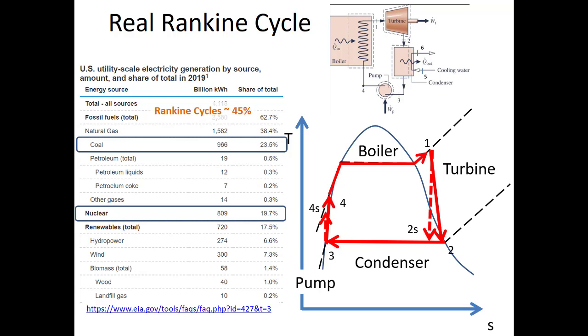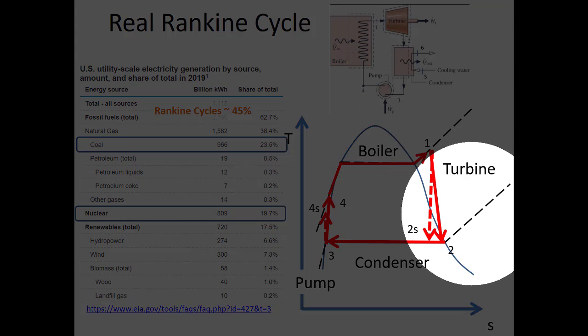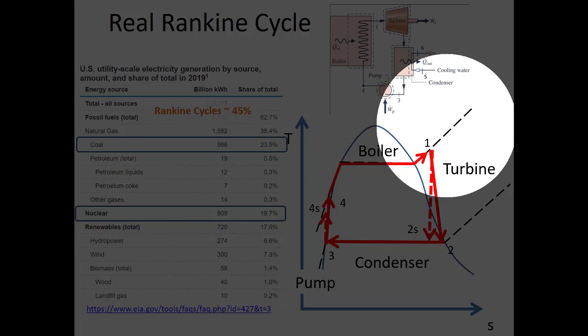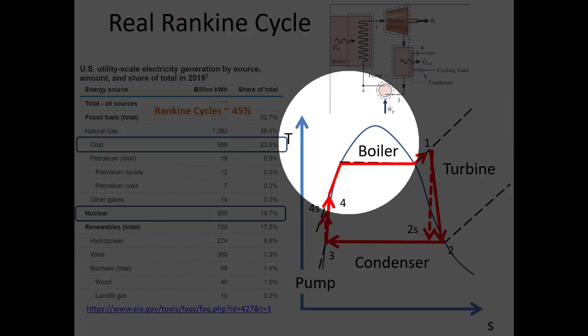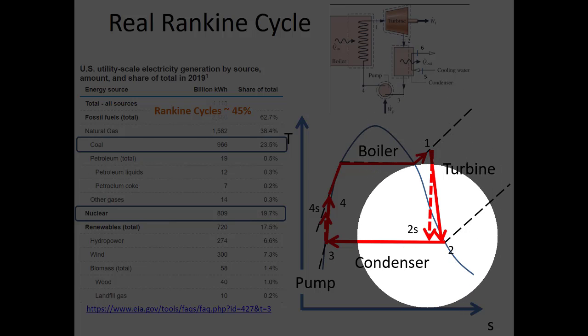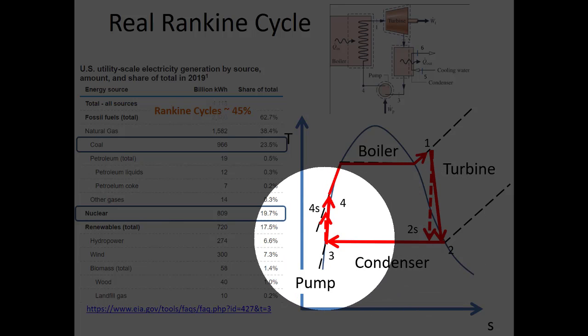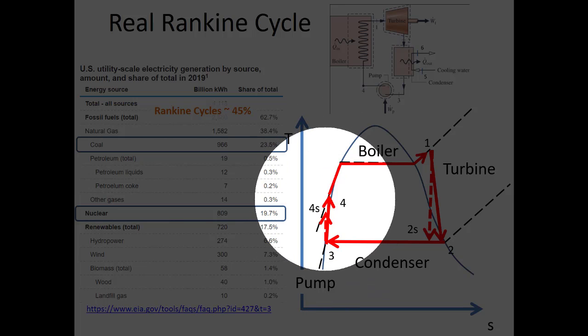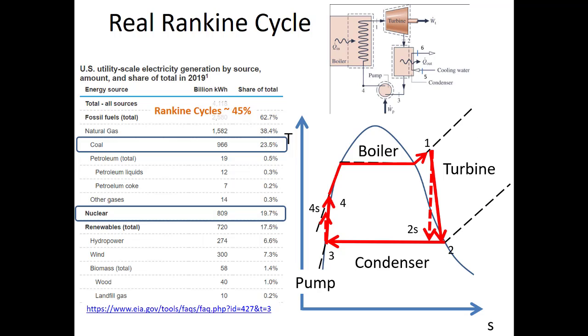And we talked about how to draw these on a TS diagram. This will be important potentially for the exam tomorrow, where a 4-part Rankine cycle operates between some low pressure and some high pressure. That's the dashed lines here. And we're going back and forth across the vapor dome from steam down to maybe a high quality saturated mixture. And then we condense down to a saturated liquid, right? So we've gone from steam to liquid to increased pressure. And then at this high pressure, this is where we add heat and we boil that water.